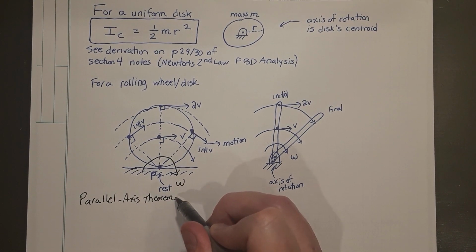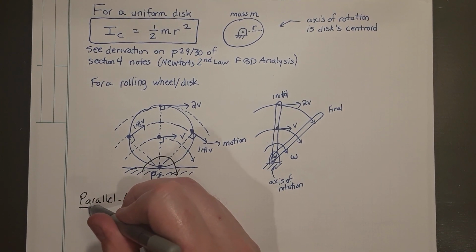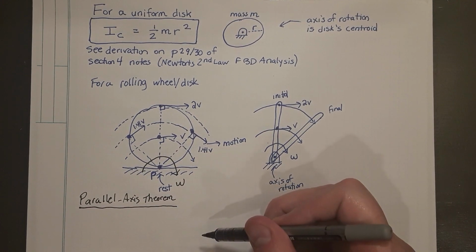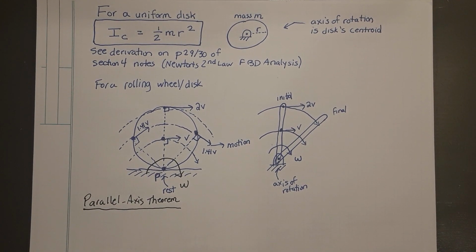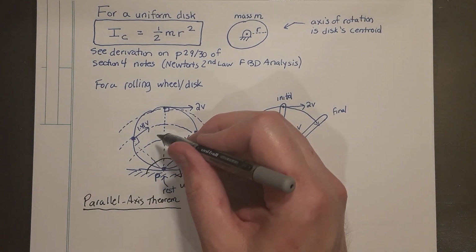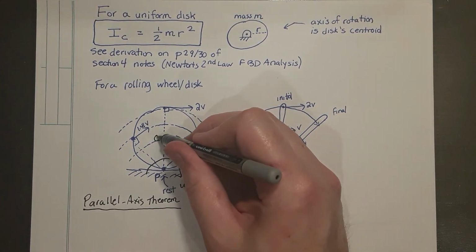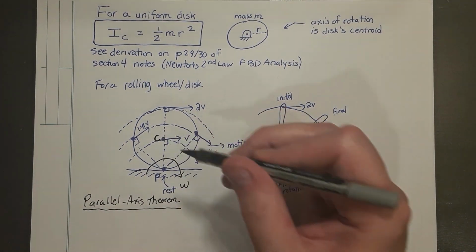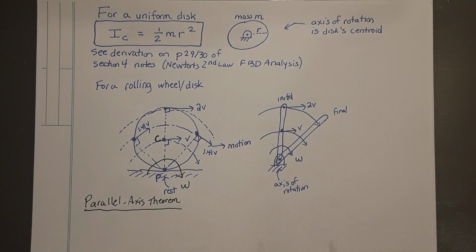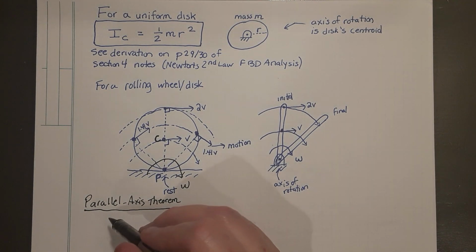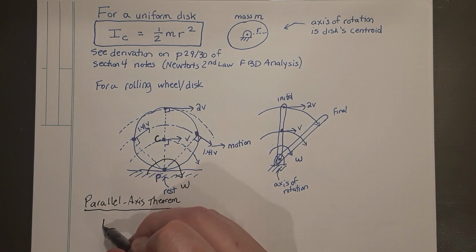This is the method by which, for any two-dimensional plane motion of a rigid body, if you want to calculate the moment of inertia of the object around its new axis of rotation P in reference to its moment of inertia around axis C, the equation is relatively straightforward.